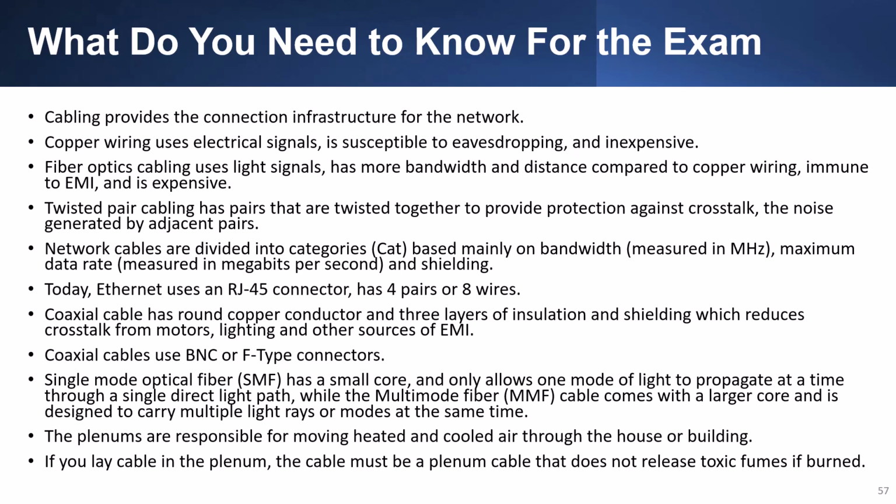The plenums are responsible for moving heated and cooled air through the house or building. To lay cable in the plenum, the cable must be plenum cable that does not release toxic fumes if burned.